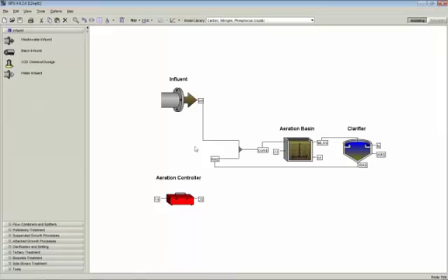This was actually based on a real project that I worked on about, boy, it must be 9 or 10 years ago now, for an industrial situation. So I've modified the layout a little bit to make it work for municipal concentrations. And this was a CSTR clarifier, pretty conventional activated sludge, except that it had an aeration controller, and they were setting a cycle so that it would aerate for a period of time and then turn the air off and let it be anoxic for a period of time. And they were trying to maximize total nitrogen removal by getting nitrification and denitrification in the same basin. And they did that through this cycling system.